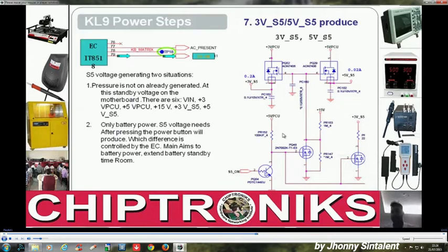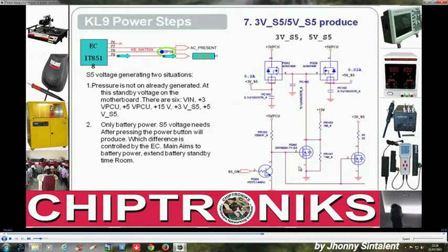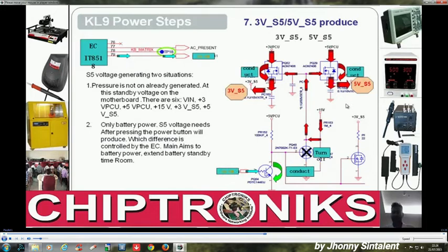VGS positive. But here, if you see this signal, it is getting a shorted path, the entire current will flow across this, the entire voltage will drop because ground would come over here, so there would be 0 voltage. So you can see this VGS would be 0, so this MOSFET will be turned off. So in that case, what would happen?